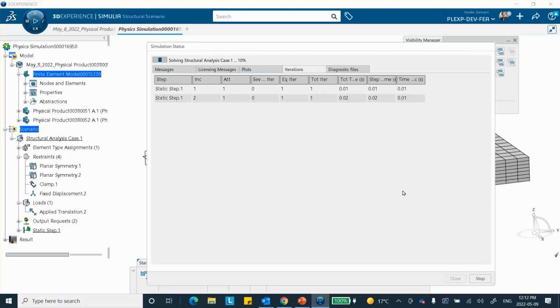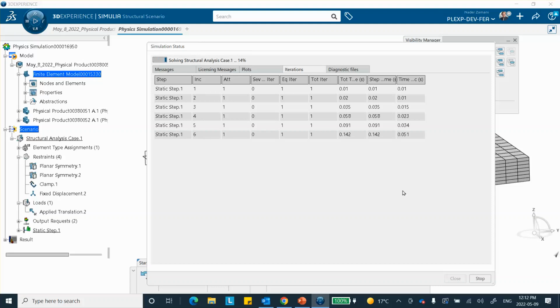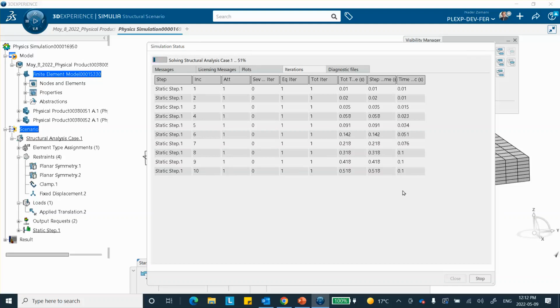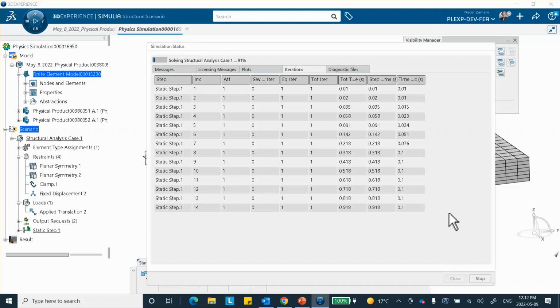As you can see, all these steps, if you're familiar with ABAQUS CAE, all these steps are one-to-one. There's one-to-one correspondence between this interface and ABAQUS CAE, except that they look different. And not everything is available, such as plane stress and plane strain is available in CAE, but not here. I was told that in the recent release R2022x of 3DEXPERIENCE, axisymmetric model has been incorporated, but I'm not sure whether it can do contact problems or not.